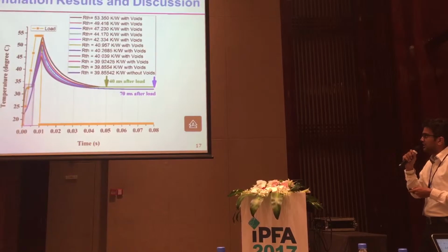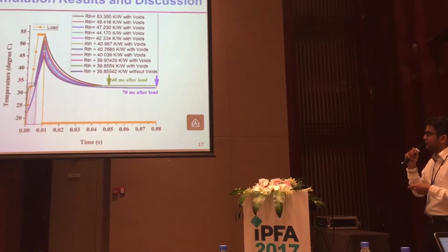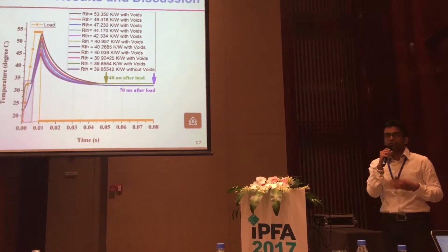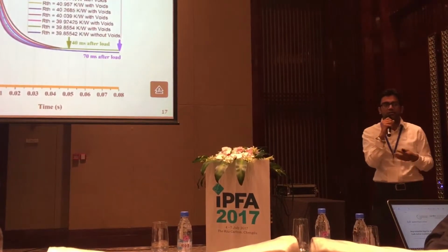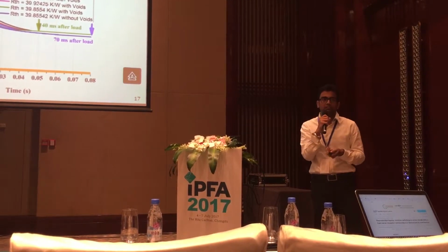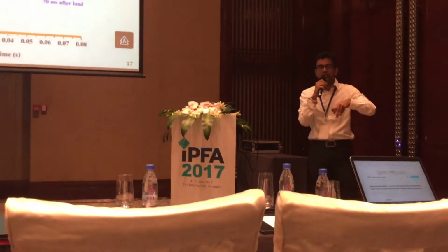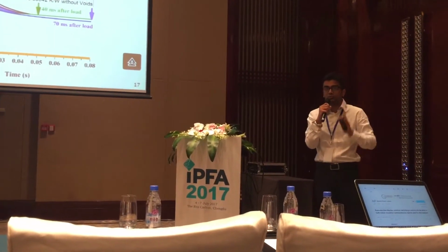So we can see clearly distinguished curves, and we can screen out diodes with and without solder voids very easily, as shown by the previous values also. But this work takes RTH into account, not only del VF, but del VF and RTH both.